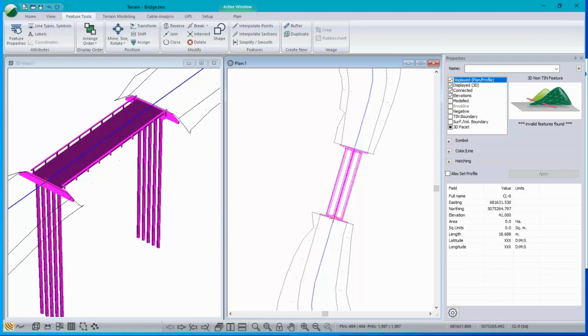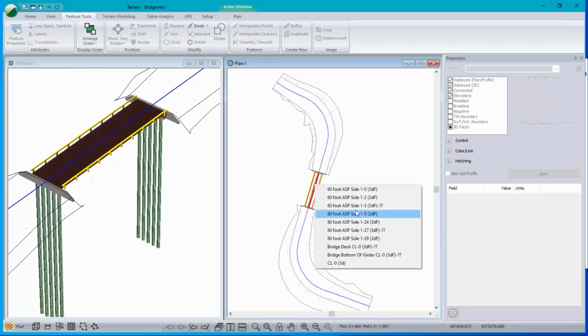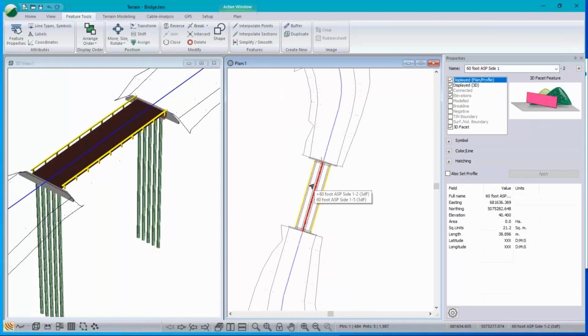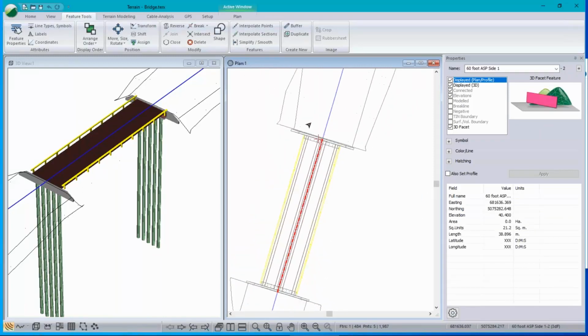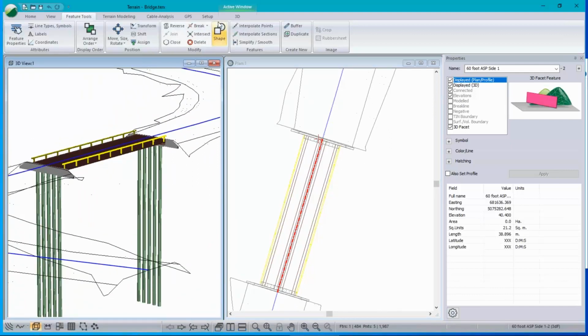But if you do manage to select it all, this object can be stuck in the middle of an alignment, and you can see it in your location module as a background in the 3D views and so on. It's a very powerful tool. So similar to the symbols, but not the same. That's using our 3D facet property. Facets are planes, and you have to build a collection of planes to make an object like this. Not for the faint of heart, but once it's saved as a terrain, then it's quite easy to use.